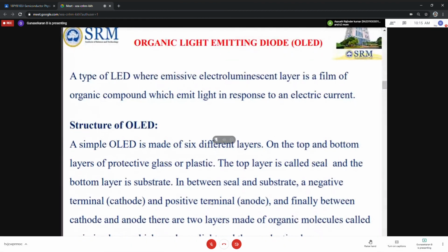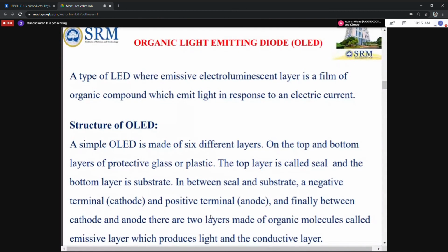So how? The PN junction is connected to forward bias, and the carriers cross the junction. The majority carriers that cross the junction act as minority carriers and recombine with the majority electrons and holes. You get the light radiation. So that is for normal LEDs, which you already discussed.